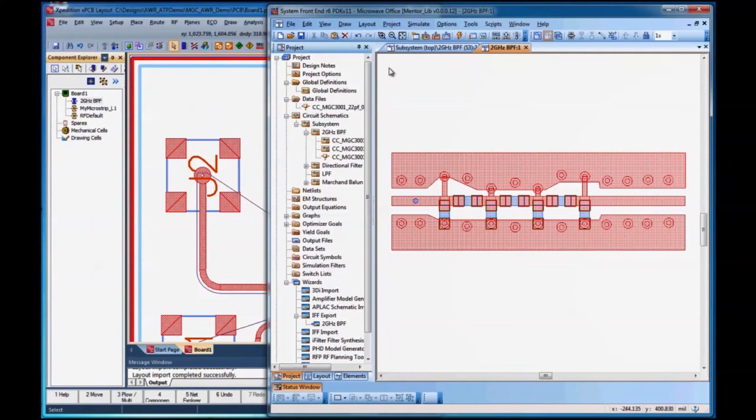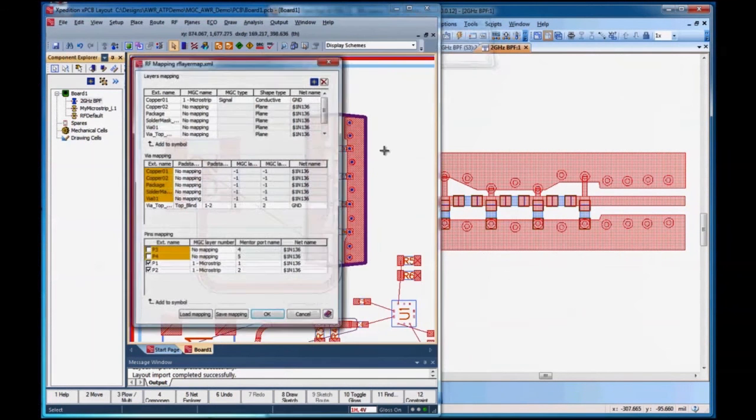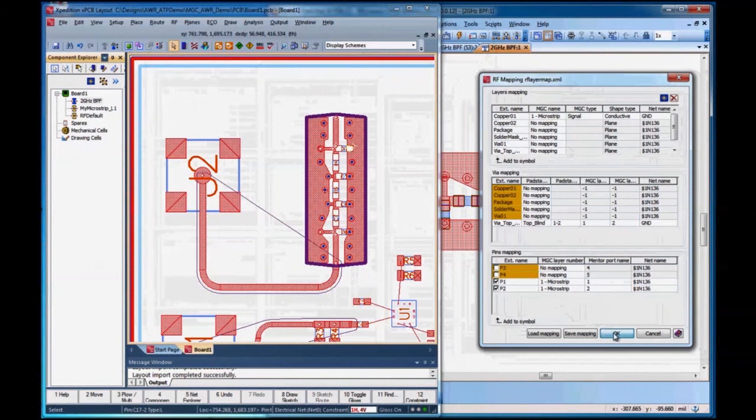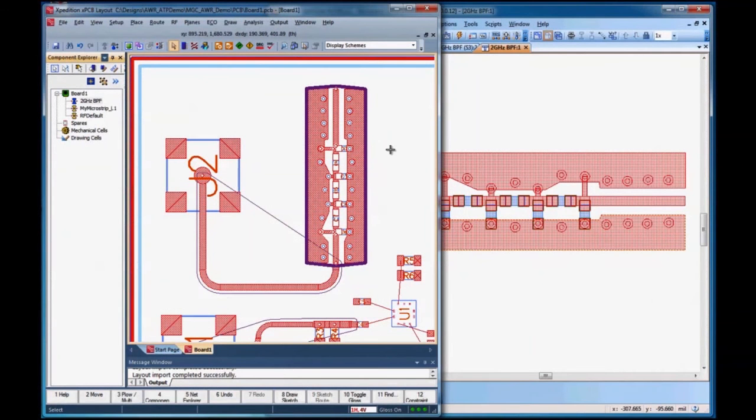Now what you want to do now is export that particular design element back into PADS Professional. So you can see that's what we're accomplishing now. We're picking all those elements and importing them, and you can see now that I've been able to reproduce in PADS Professional the same copper structure that I was using before. The changes to the schematic can then be made to the schematic and updated.